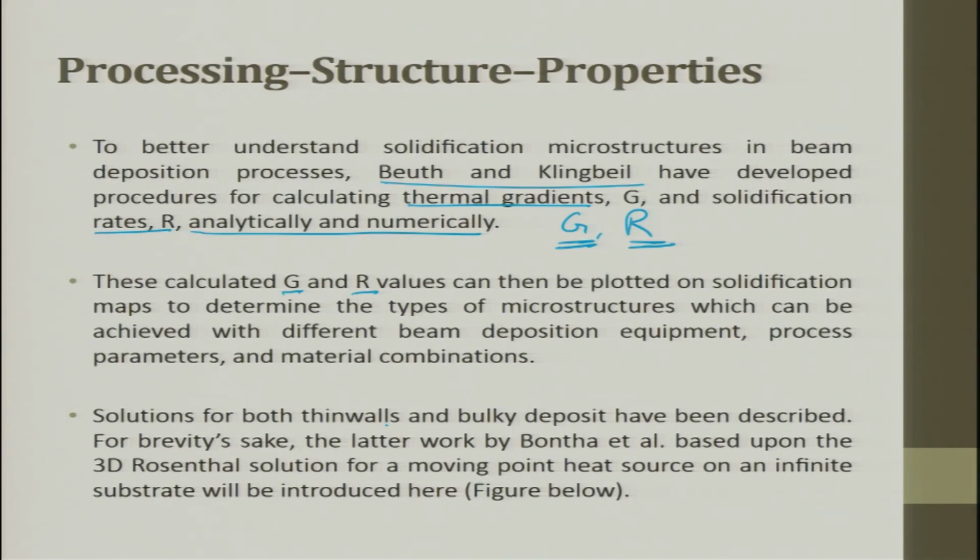The solution for both thin wall and bulk deposition has been described. For brevity's sake, a later work of Bontha et al., based upon the 3D Rosenthal solution for a moving point heat source on an infinite substrate, will be introduced here.